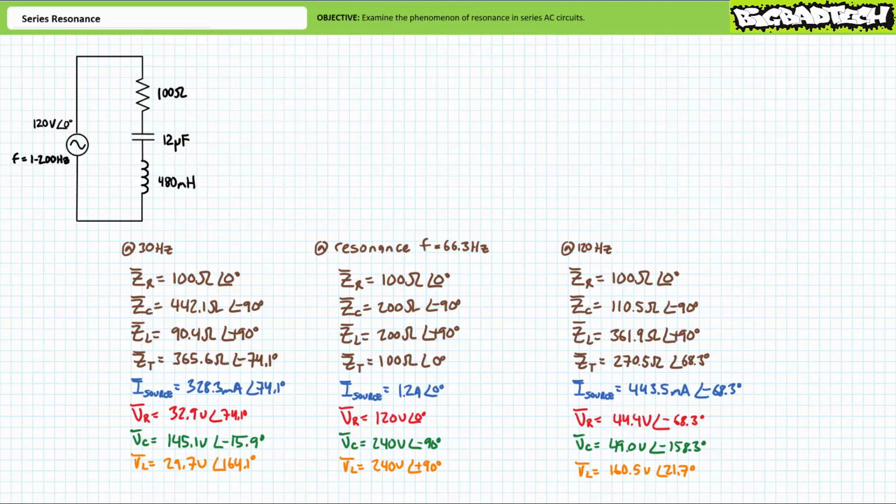different series circuit because the impedance of the reactive capacitor and inductor change. If excitation frequency increases, we should expect the capacitive impedance to decrease and inductive impedance to increase. As such, we should expect the series circuit to exhibit a slightly inductive nature. Let's see if this is the case.